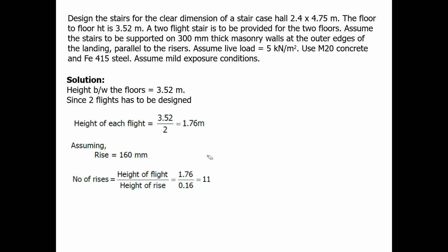So what about treads? Is there any formula to calculate the number of treads? Number of risers minus one. Okay, good. So number of treads is equal to number of risers minus 1. So we'll get 10 numbers. Okay. Finished?